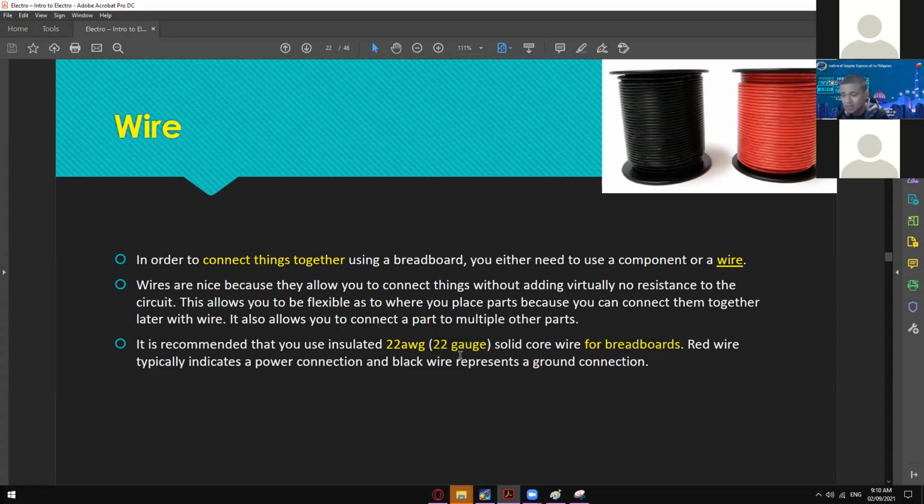You can use a higher or lower gauge, but take note that it might cause an issue. A higher gauge will eat up more voltage, because as we all know, wire also has a resistance. The longer the wire, the more voltage drop it has.